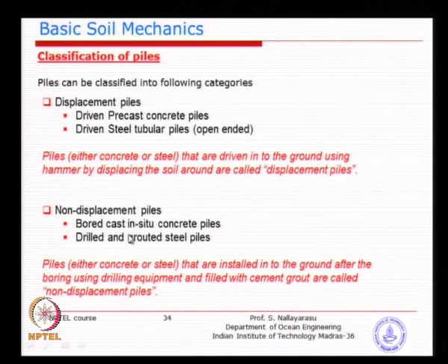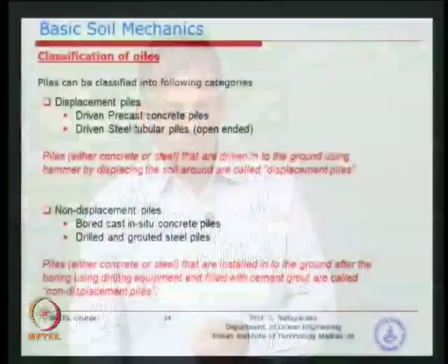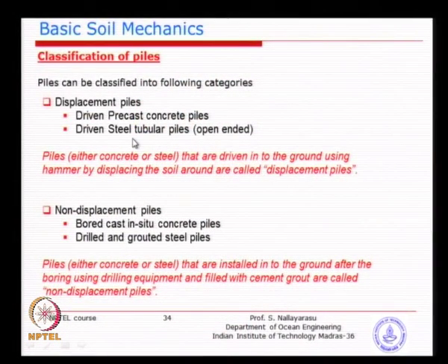Mostly we will not go into calculation of bored cast in situ and drilled and grouted piles. Basically, it will not be applicable to the offshore platforms, whereas we will use the driven steel tubular piles, in fact 100%. You will not even think of using concrete piles for offshore platforms. Concrete piles are purely applicable to the coastal and near coastal structures of smaller water depth and maybe reduced loads, but for offshore structures, even if it is located in 20 meter water depth or 30 meter water depth, we will not use any other piles because the magnitude of loading is larger.